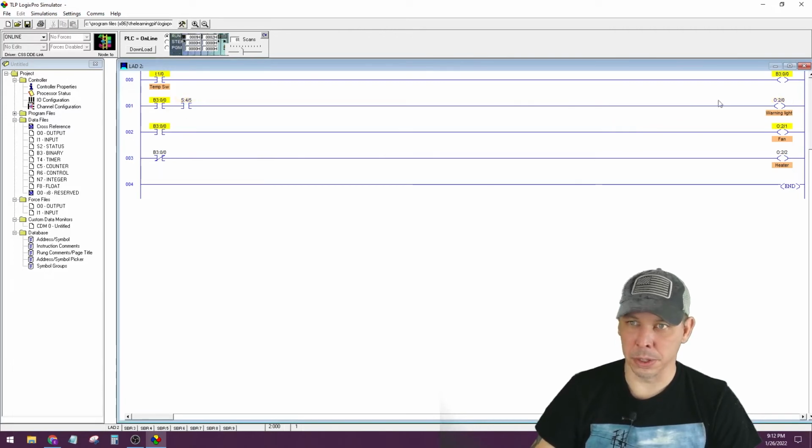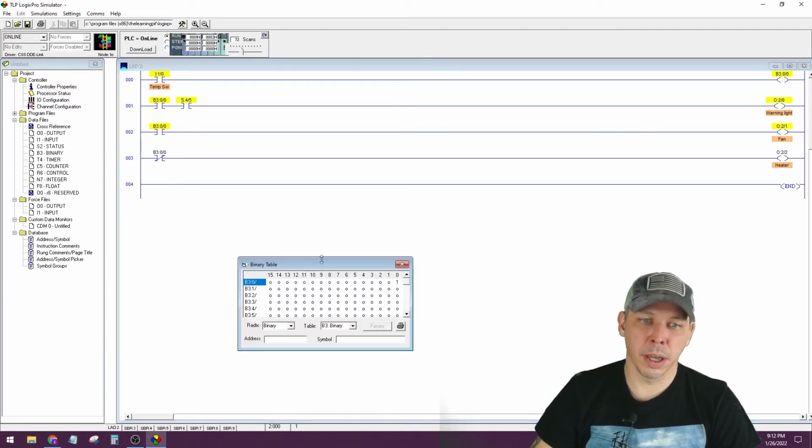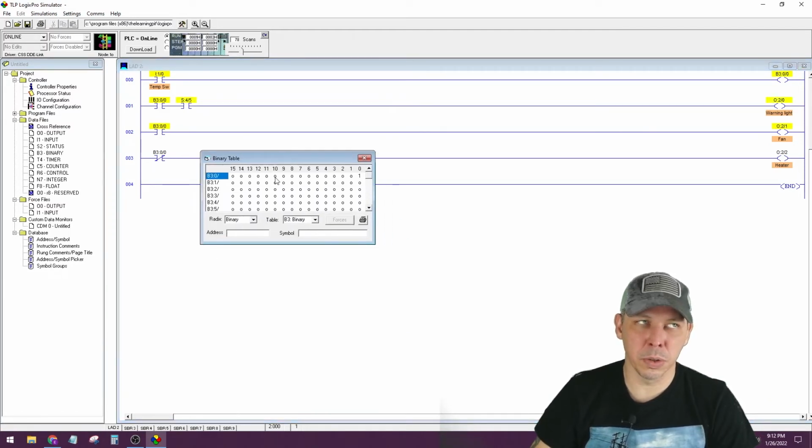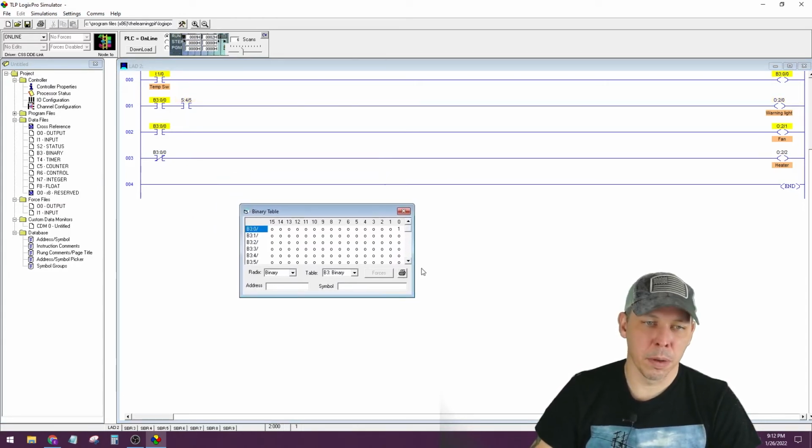They're all just going to switch state whenever you energize or de-energize that bit location. And you're not really energizing or de-energizing it like you do when you say that. Generally you mean a coil and a relay or a contactor, but what you're really doing is just changing the state of that bit location from a 0 to a 1 or a 1 to a 0. So then it goes to the second rung, and it evaluates the left-hand side.